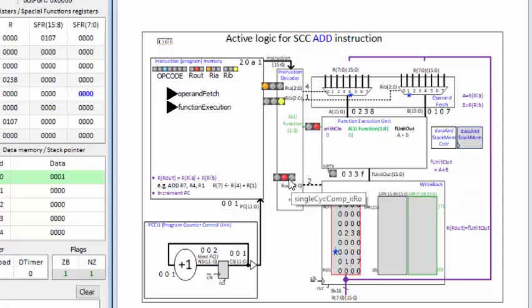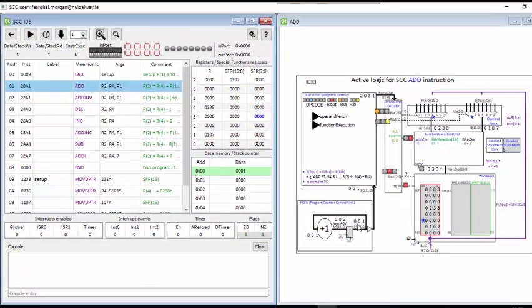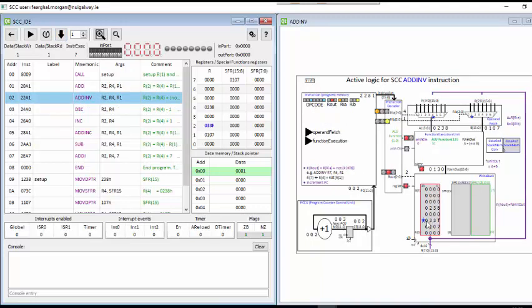The destination register is register 2, as is seen over here, and the field here is 8 to 6 in the instruction register. The opcode is here. This writes into the registers with the red box indicates that this is the active register bank. Register write is asserted in the instruction decoder, and it will write to register 2. The program counter will increment. So as I single step, the value now in register 2 is 33F.